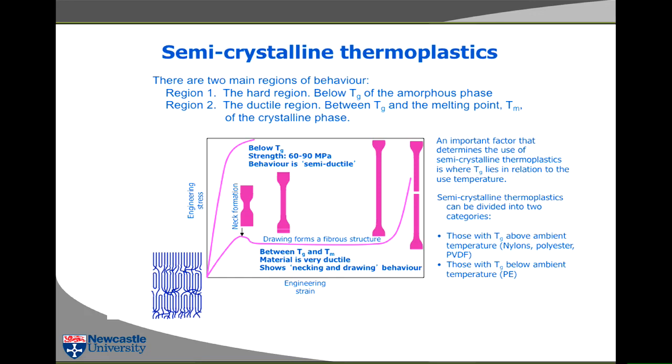So all these thermoplastic molecules align up on the neck. The material effectively work hardens, so this neck is actually stable. It will yield here, and there's a load drop. It will yield, this is the neck which forms in the sample. And then this necked region will propagate all the way along the sample.